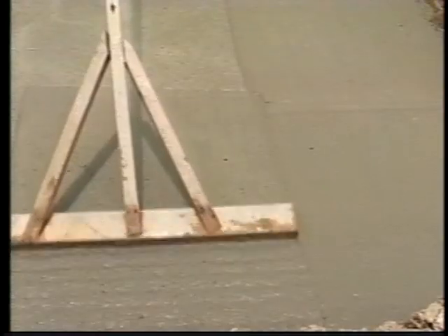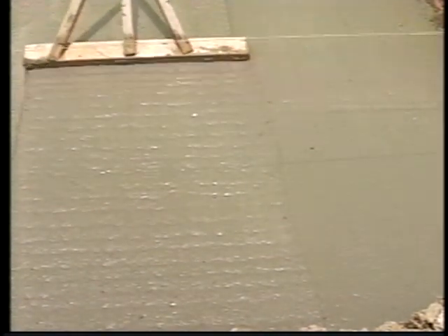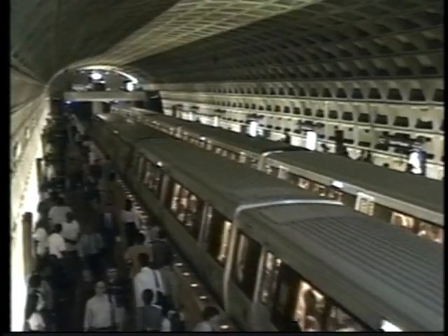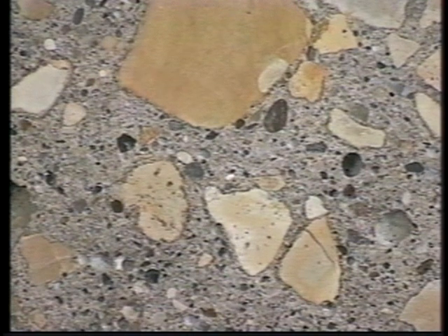Its structure is complicated and random over 9 orders of magnitude of length scale, as we will see in this video. When seen at a length scale of meters, concrete does indeed seem to be a simple, homogeneous mass. However, as we zoom in on the material itself, its complexities become apparent. This cutaway view of a typical concrete is about 50 millimeters across. Concrete at this scale is a composite with a cement paste matrix and inclusions called aggregates.